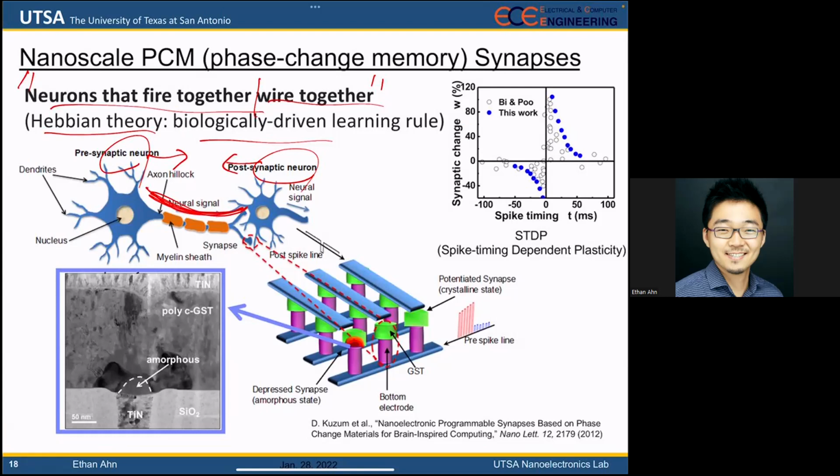So the research question here is, can you represent this somehow with emerging memory devices or emerging nano devices? And yes, here, for example, we again have this technology called PCM. What's changing here is, you see, we have this amorphous material region, which is kind of dome shaped like this, and all the background material is still the same material, but in a different phase.